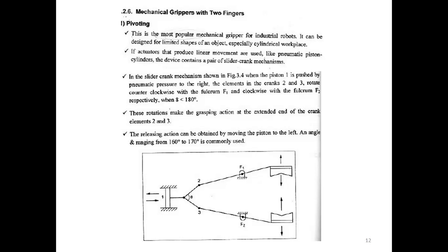The pivot method turns the robot by driving both motors in opposite directions. We have other ways to turn the robot, but this method results in a perfectly tight turn because the robot's axis of rotation is centered between its tools. And when we talk about the gripper mechanism, it is a rotary actuator, placed at the cross point of two fingers. Each finger is connected to the rotor and the housing of the actuator respectively. This produces grasping and releasing actions.